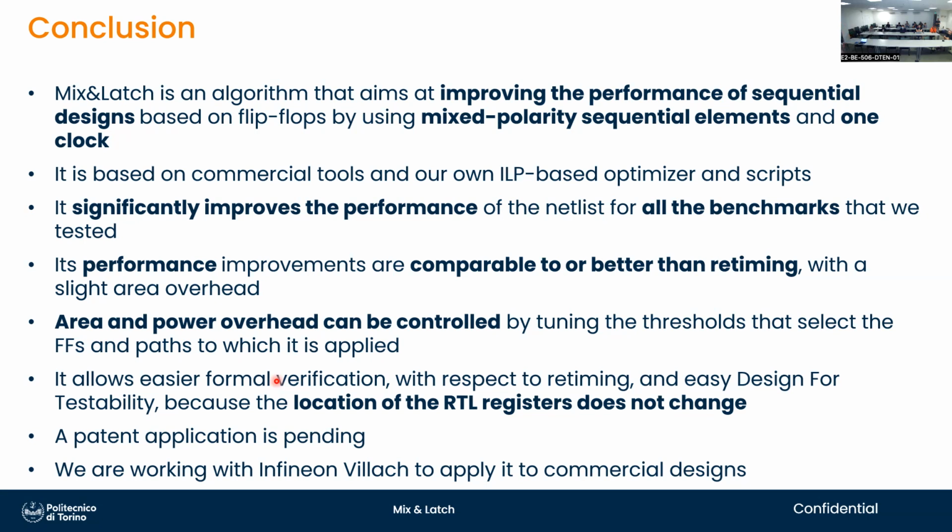I mean, the layout problems that we are generating are not different from those that a regular place and route tool has to handle when dealing with a regular synchronous flip-flop based design. Nothing fancy or more difficult. Unlike asynchronous circuits, which I worked with earlier, which are a little bit more difficult to handle. But these are still synchronous, and those tools know how to handle clock skew and so on, also with latches, not just with flip-flops on the place and route side.